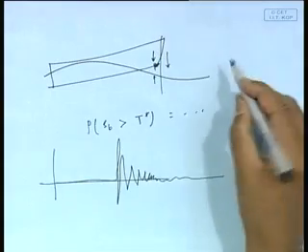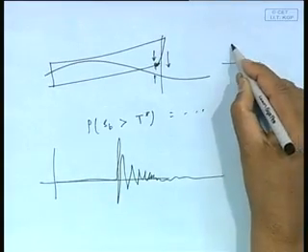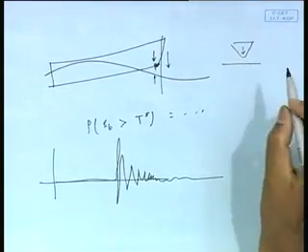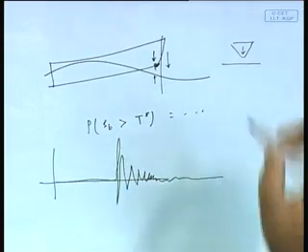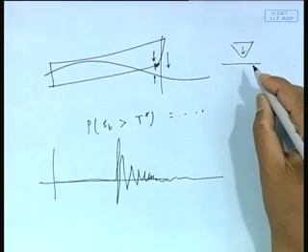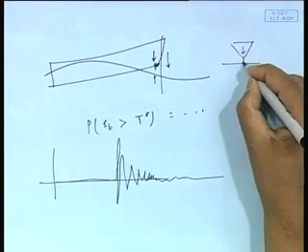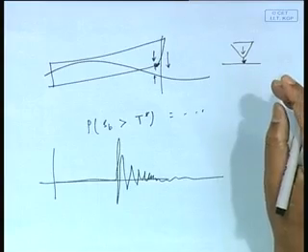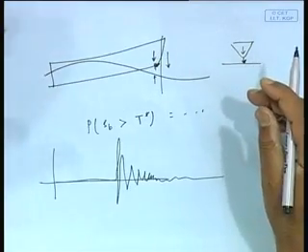Suppose you take water, and something is dropped. If you drop it from a much higher height, you will expect much more impact. Why? Because the entry velocity has something to do with it. If you are very slowly entering a wedge from outside into water, you don't expect a very large load, but if you enter very fast, you do.